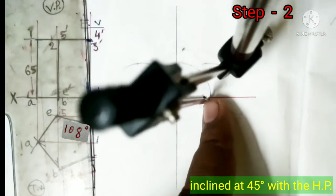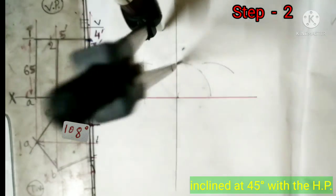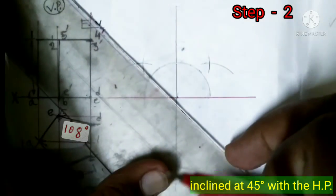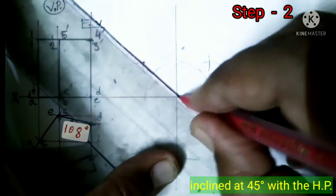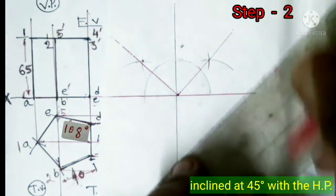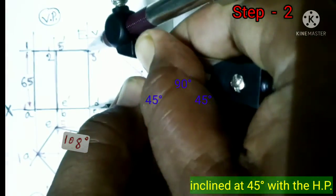Also take the same radius and again draw two arcs of the same radius, taking the end point of the radius as a center. Join the center point to the intersecting point between the two arcs by a line and then extend it. So these two angles will be 45 degrees to the XY line. Then draw the front view in this condition.